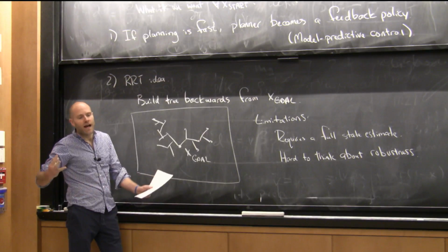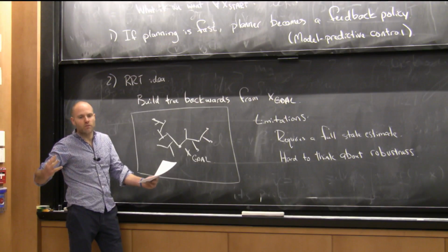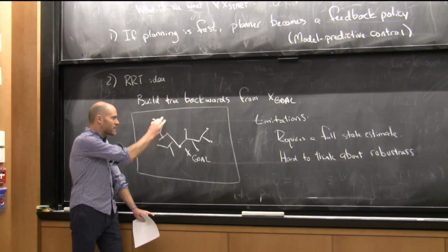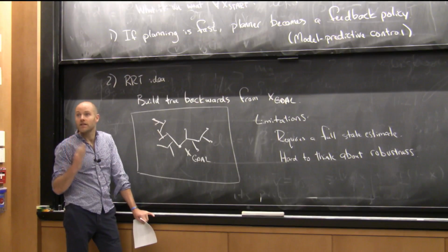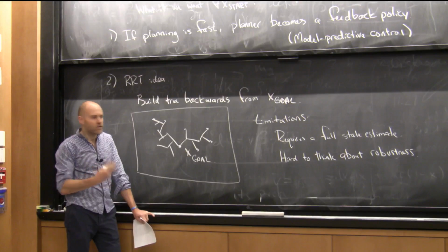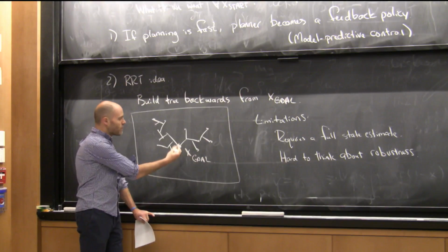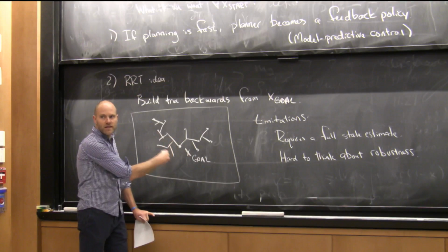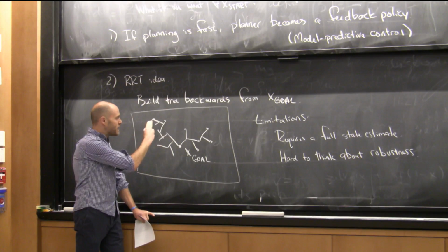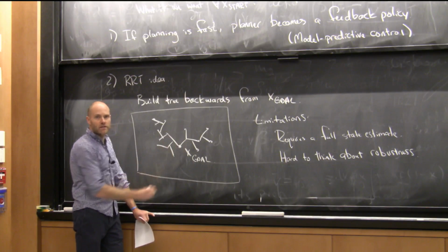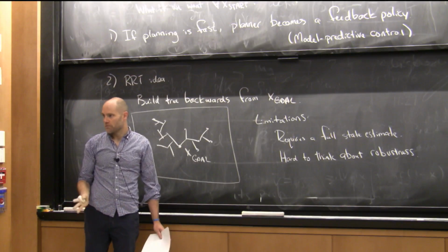With a feedback controller, I can ask how it performs given the model parameters are different, because there's a defined action for every initial state. But if my entire premise, my entire path is now invalid because my model changed, then how do you ask questions about robustness? It's not just that the representation is hard to think about, it's that it's baked in this notion of a feasible trajectory that may not be valid if the model changes, right?